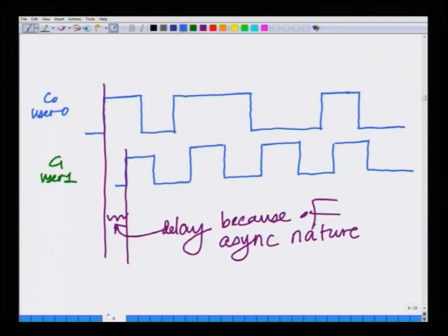Let me go back to the diagram. Let us call this delay a fraction f. I am going to call this delay here a fraction f, assuming that the total chip time is unity, is 1. This delay is a fraction f of the chip time. Now, if f equals 1, then this moves by 1 complete chip, hence again they are chip aligned. Alright. So, R01 again becomes synchronous.